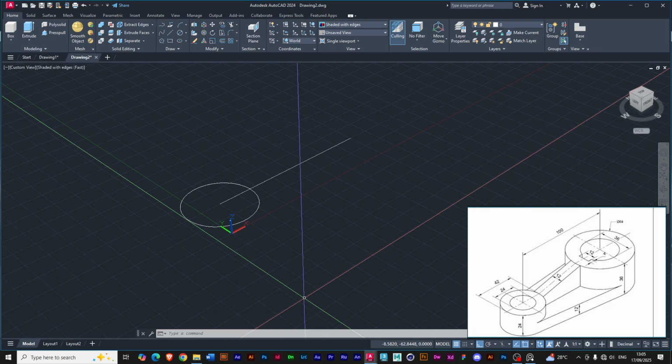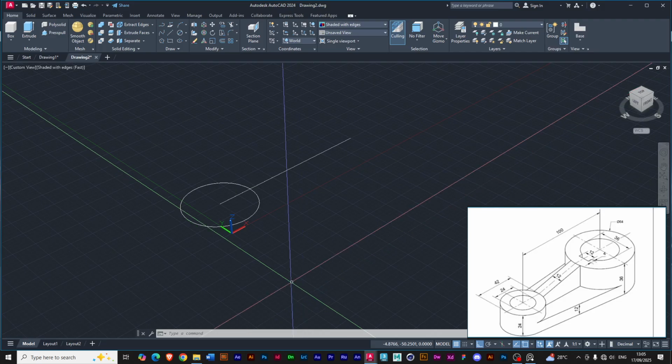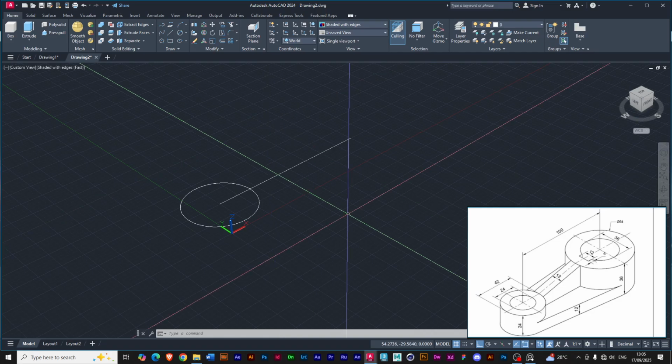All right. So we want to get this other circle, the bigger one, based on that line. So we use the circle tool again. You can use your up arrow on your keyboard to access the tools you've just used. So you will see circle in one of them.